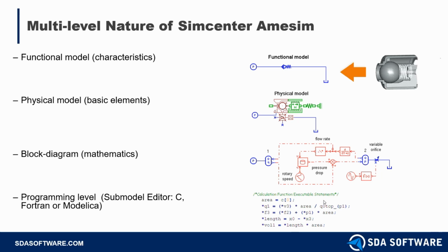And besides that, Amesim also allows your engineer to define their own components. You can do it by the block diagram approach right here, or you can just go to the submodel editor and edit it on the programming level.